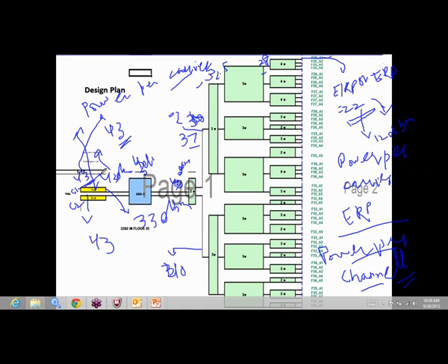So 43 minus 33, it's 12 basically. Whatever ERP I got on the basis of power per channel or power per carrier, I will reduce 10 dB because my CPICH is usually 10 dB lower. Or let's say my CPICH is not 33. This is 43, but my CPICH is 30 for any reason. I have configured my CPICH to be 30 in UMTS. So if I have configured it to be 30, then the difference between my power per channel and my CPICH is 13 dB. So I will deduct 13 in that case from here, which will make it around 9 dBm of ERP. Okay.